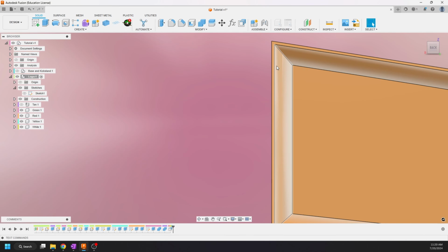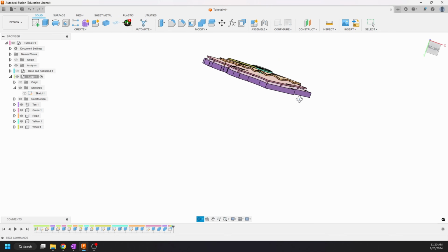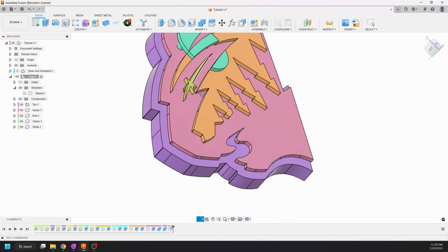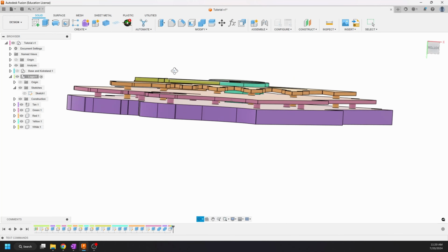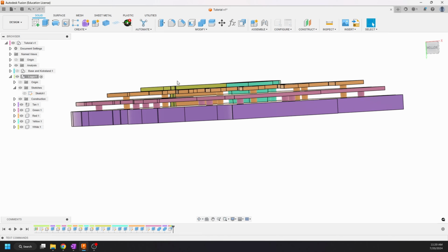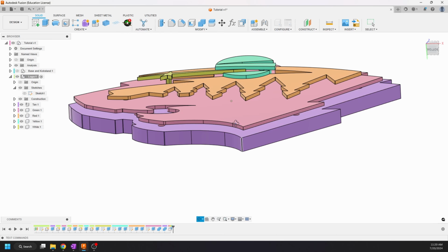This is the taper, and then this is the tolerance offset that we just applied. We can turn the tan on, and that's why I'm saying that the offset part is not hard, because we're not going through and doing every bit individually. And that's another important reason to have all of these pins extrude the same depth. That way you can just select them all together.